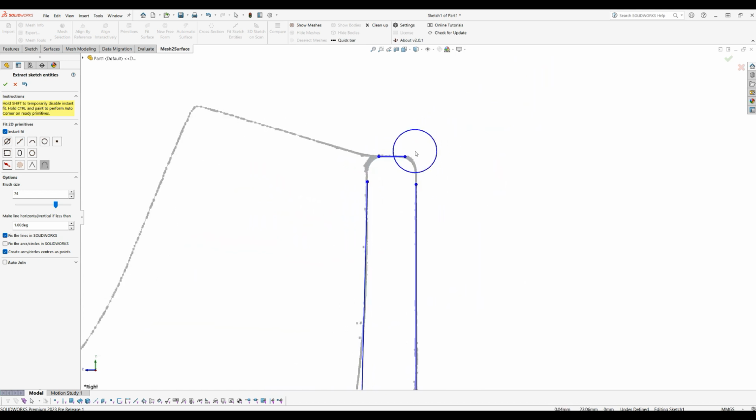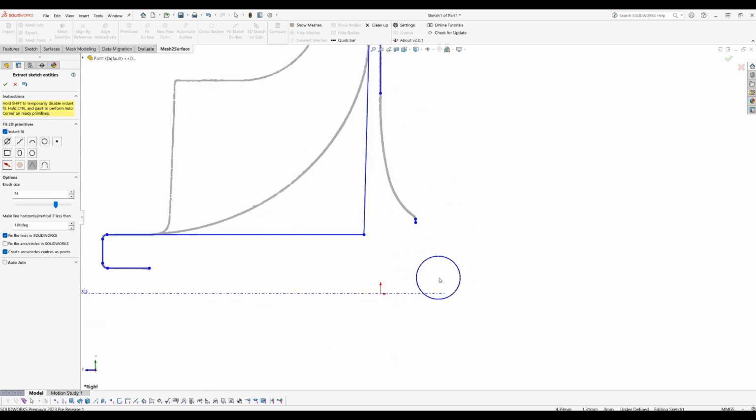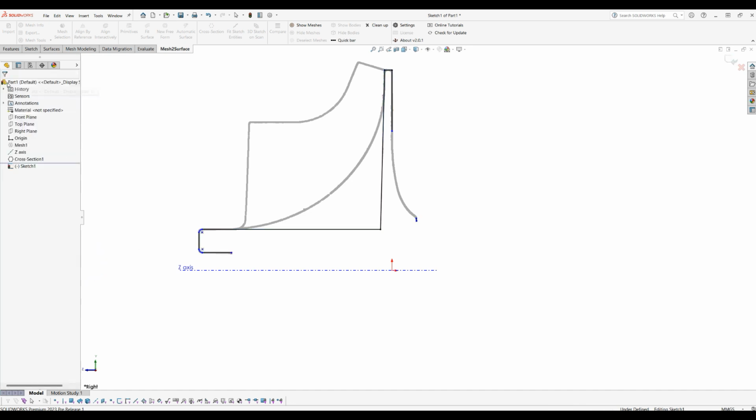What you can do here is use the intersect command. That is actually a corner trim, which is similar in SOLIDWORKS, but the way it works, you just brush over these contact points. So I'm ready for now. Before I press OK, I want to make sure that all the lines are fixed in SOLIDWORKS. When I press OK, they will appear as normal entities in SOLIDWORKS sketch.